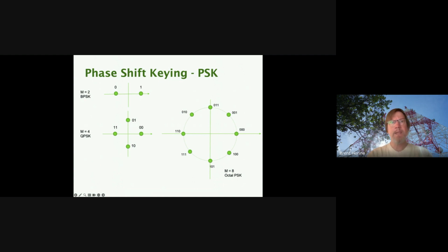And that's, as we talked about in the last exam, that makes it easy to amplify. Won't go into all the circuits, reasons, and that type of thing. Just log that in your brain, that when you have a constant power, constant envelope, right? So when you look at that RF signal, yes, you'll have a varying signal, but the max and min peak to peak value of that cosine wave doesn't change, right? So if it's plus or minus 1 volt, it's always going to be plus or minus 1 volt. The way we're encoding the information is by changing the phase.